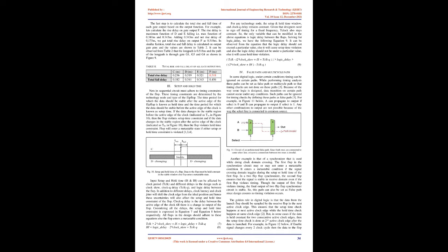For example, the net rise delay on gate output D is given by 0.040 ns plus 0.009 asterisk 10.88 fF equals 0.137 ns. The net fall delay on the same output is given by 0.030 ns plus 0.007 asterisk 10.88 fF equals 0.106 ns. The net rise and fall delay on all gate output nodes is shown in Table 1.